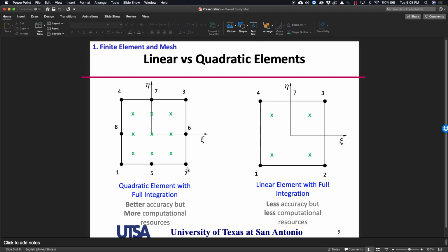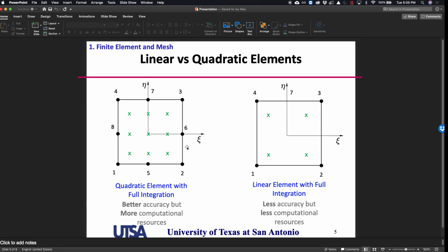So if I ask you for stresses at integration points, it's a different answer than if I ask you for stresses at a node. You can also ask for the average stress at an element, so you can have a sensation of how loaded or how stressed that element is by computing the von Mises stress for everyone and then computing the average of the von Mises stress for the element and things like that, okay?